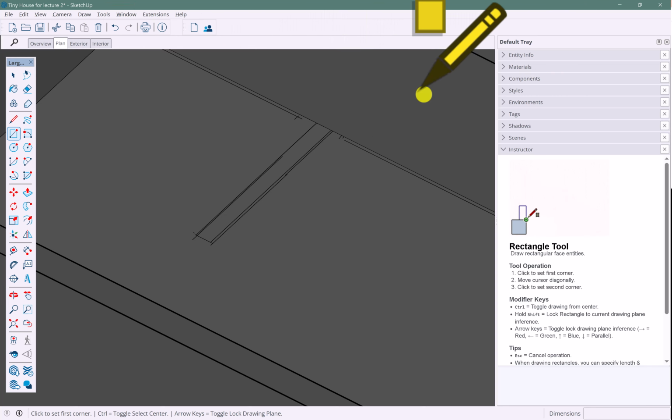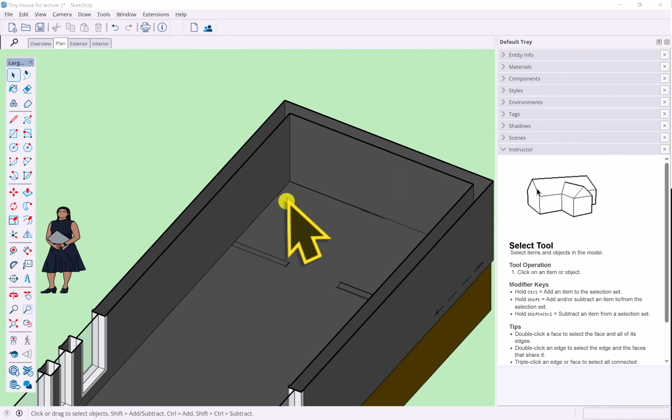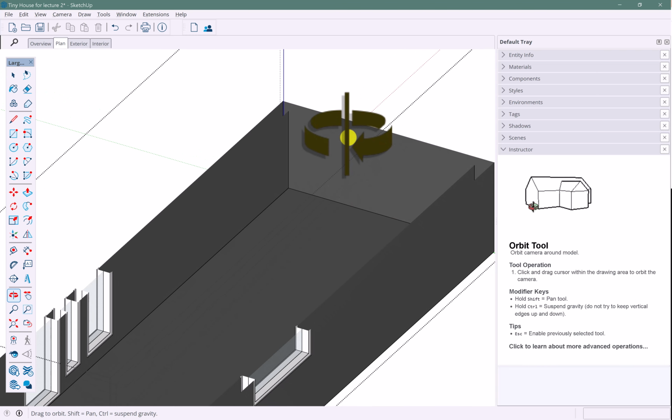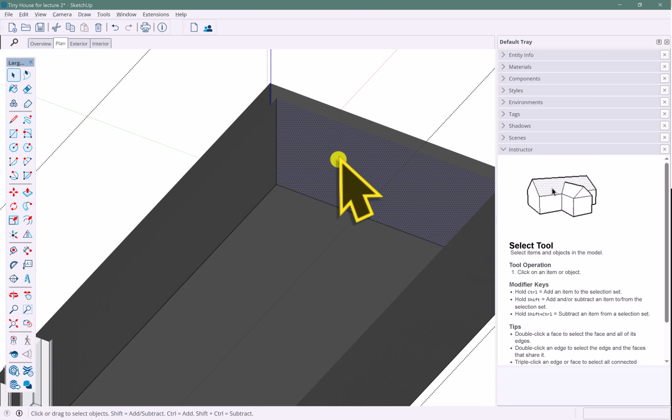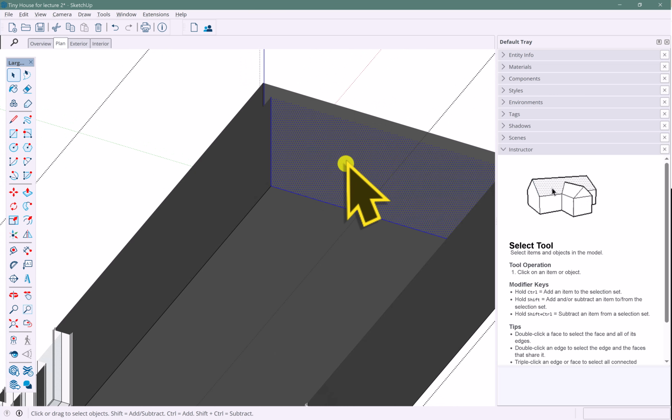I'm going to tap C to close the component so that I'm back into my model. Make the back wall, as you might remember, the roof is sloped. So maybe I'm just going to copy this back surface and use that as my interior partition. So what you can do, double click on your site, your massing model, and you can double click on this back wall. You see how I have the surface and the bounding line selected. Now I can just use the System Control C to copy. I could also use the copy button up here if that toolbar is available.